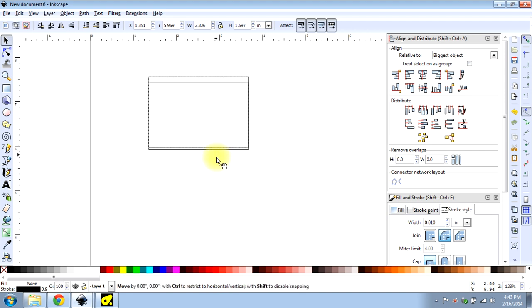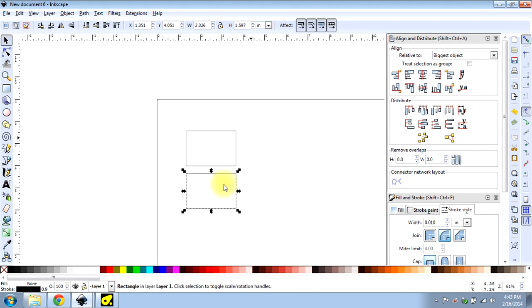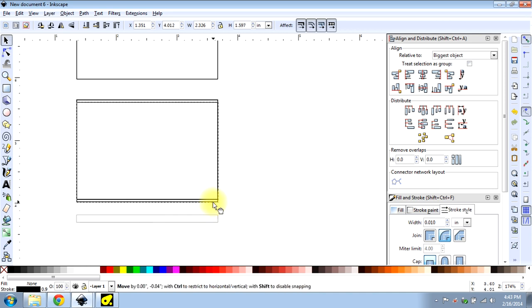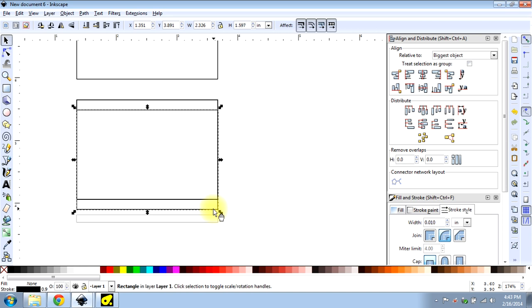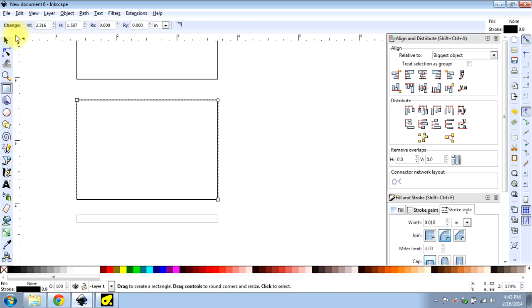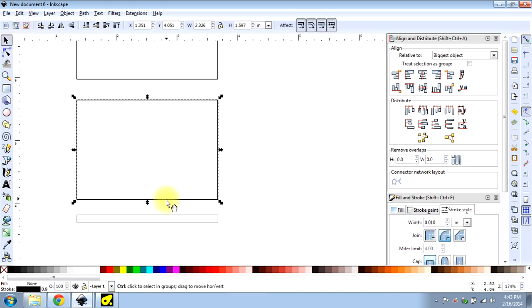Did I duplicate this? No, okay. Control D for duplicate. I'm going to hold control and pull this straight down, okay? And then I'm going to pull it straight down again. This bottom one, I'm going to set its height at 0.12. Now I'm holding control, dragging this up. That happens to be exactly the thickness of my material. My plexiglass is about...